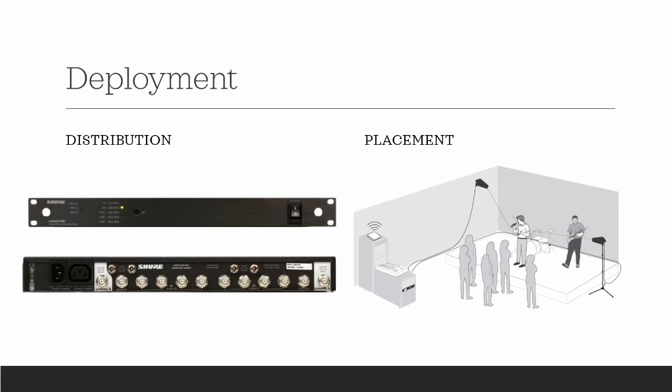The reason being is that the multipath nulls which can be created are almost minus 30 dB, which is a huge reduction in your audio signal, just because of poor antenna placement. So we want to make sure that we're doing everything we can to mitigate those risks. So that's another factor that we want to consider while we're determining the best placement for our antennas.